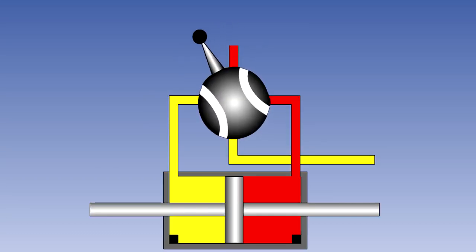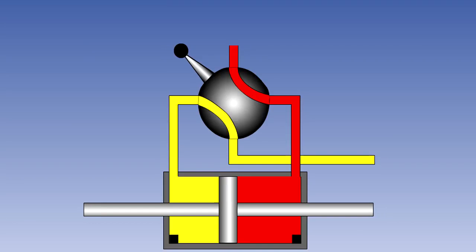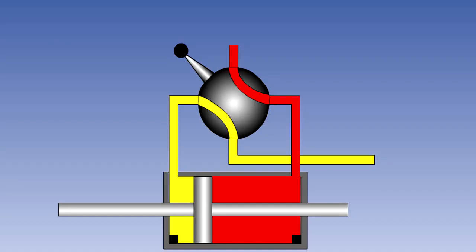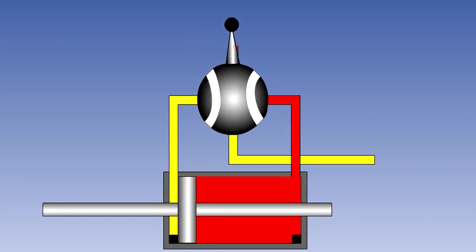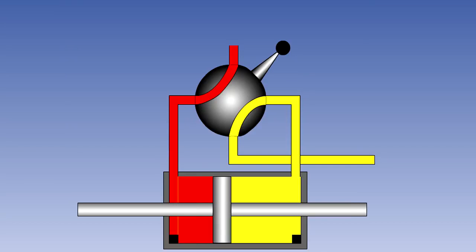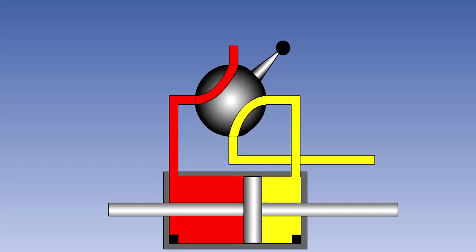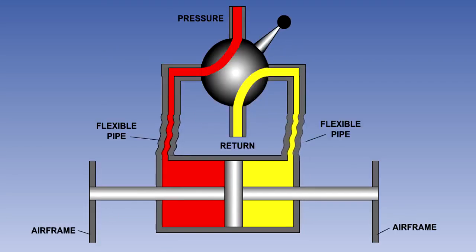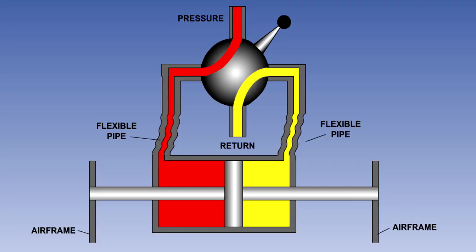A double-acting balanced actuator is one in which equal force can be applied to both sides of the piston. This is achieved by having rods attached to both faces of the piston. It is often used in applications such as nose wheel steering and hydraulically powered flying control systems. Either one or both ends of the piston rod may be connected to a mechanism, or in many instances, the rod is connected to the airframe and the body moves to operate the service.